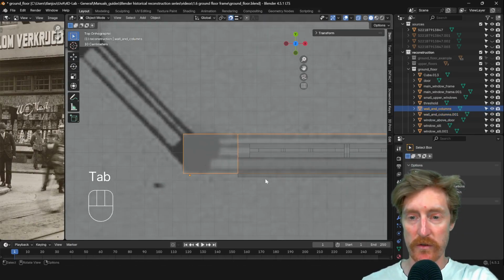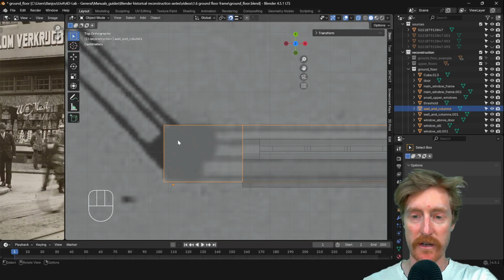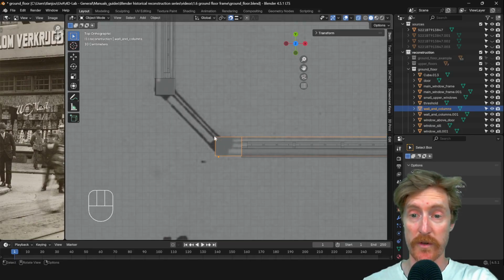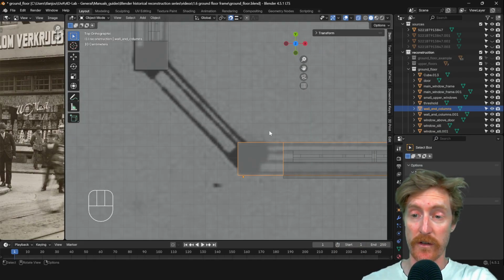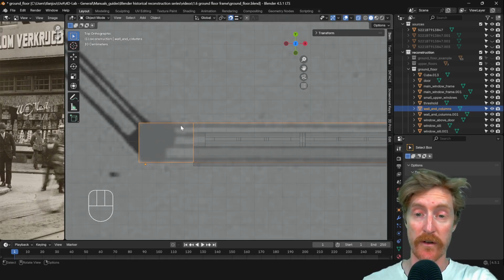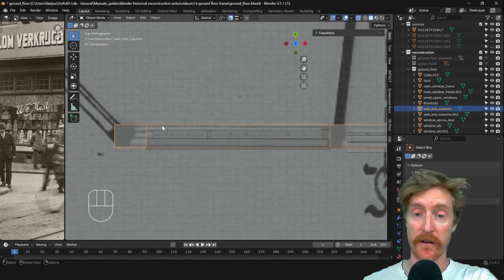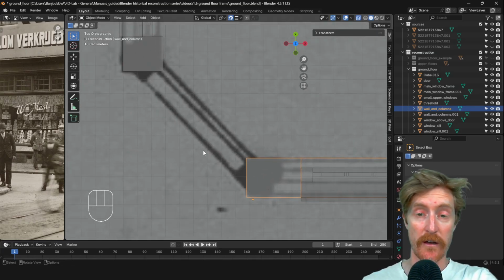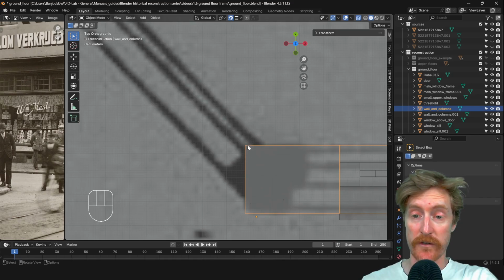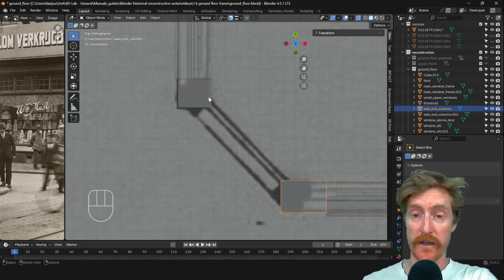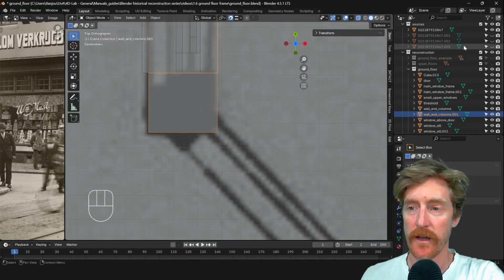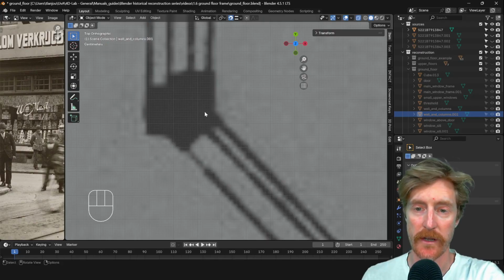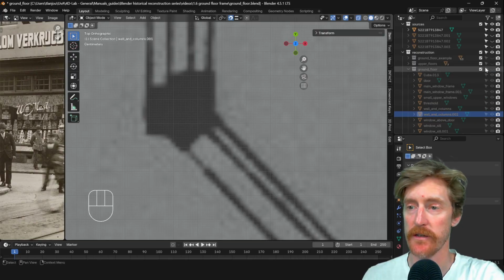It's actually also not matching here entirely, but yeah, there's a difference also between the front view and the plan drawings. Basically, we're not gonna worry about that now, because if we want to modify that, we have to modify our entire window frame, and we don't want to do that. So we're just gonna concern ourselves with modifying these sides. So how are we gonna do this? Well, first we're gonna have to make a cut from here to there in our post, and then use that face to extrude in that direction.